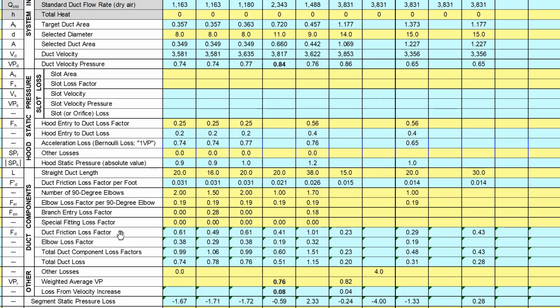Now at this point, we want to achieve a static balance between these two ducts. And we can do one of two things. We could either balance with a slide gate, or we can balance with the ACGIH balance by design using the velocity pressure calculation method. Well, balancing with a slide gate would be pretty difficult because there's not a lot of daylight between these two values.